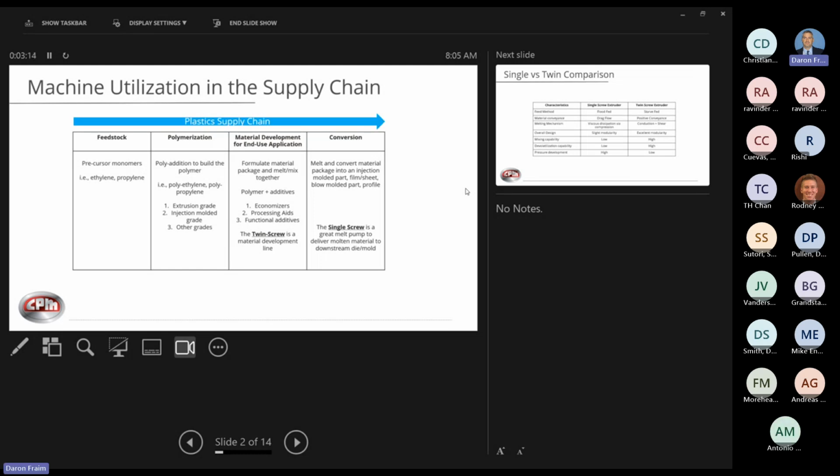And then your functional additives are normally to enhance the property. So if you're trying to add mechanical strength, reinforcement types, anything outdoor needs UV protection, your electronic type components usually have to meet certain flammability ratings, so flame retardants, things like that. And that's what the twin screw essentially is. Its dominant player is its mixing capability to really melt and mix these diverse formulations.